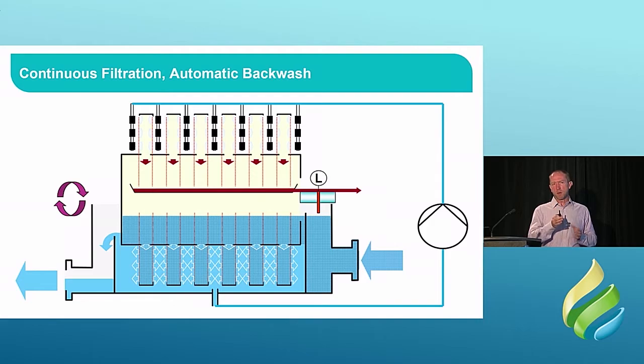The other motor that energizes is in a backwash pump. That draws water that's been stored in that reservoir, filtered water, pumps it around through spray nozzles that spray water from the outside of those discs, and that knocks off the material that's built up, the sludge that's built up on the inside of those discs, and it gets collected in a trough and flows out by gravity.